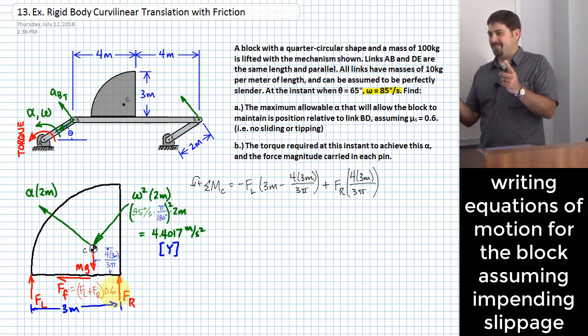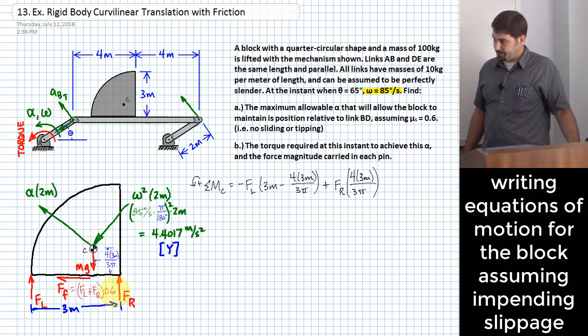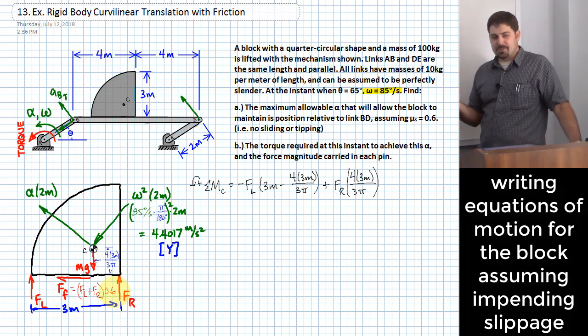Well, kind of like the normal force, right? It's another way of saying it's the normal force, but that's what it ends up being. So if they're equal, wouldn't it slip? Or is it at the point right before it slips? Right. So if we make it equal, one of the phrases we use for this is impending motion. This is the threshold where it might start to slip.